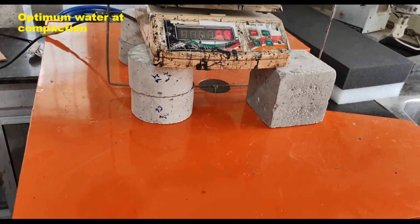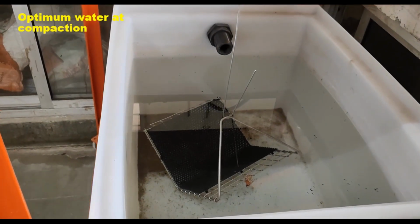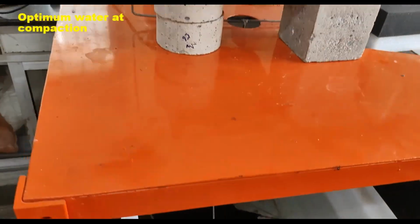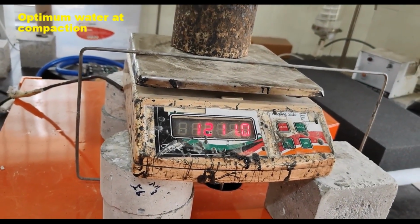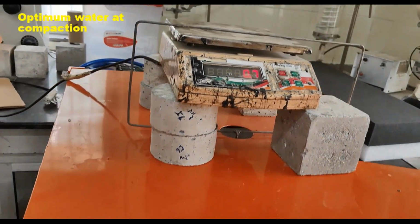After extruding from the mold, determine the bulk specific gravity of the specimen by taking the weight of the specimen in air and in water as per ASTM D1188 or D2726.